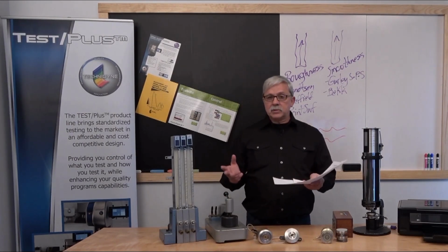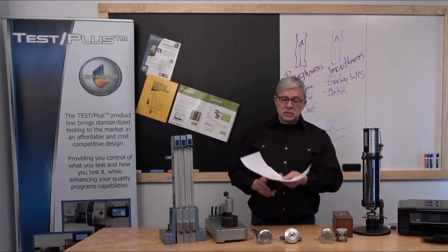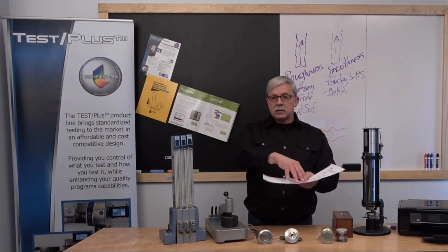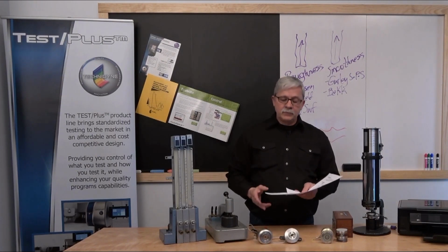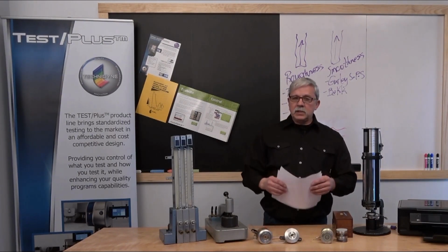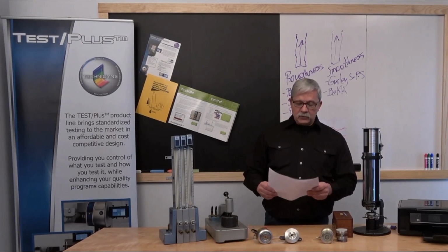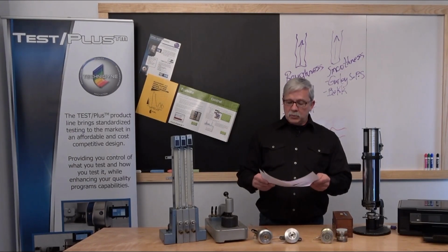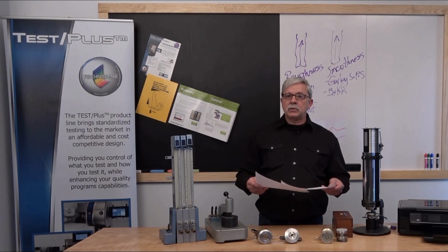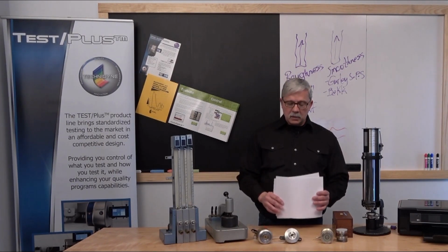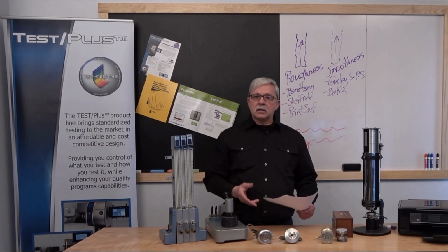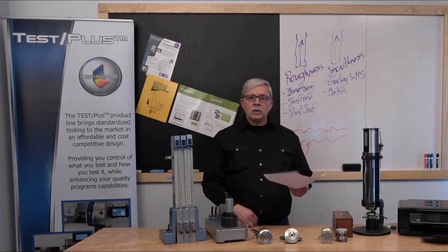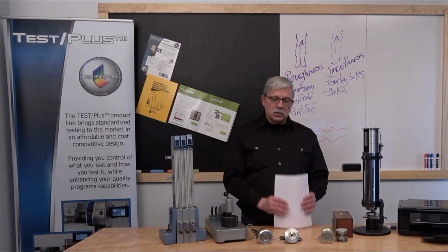I'm sure maybe once in a while you've seen that, where your printer has ejected that document, but it comes out with 2 pages. Some of the document is printed here, some of it's printed here, and so forth. So we all have seen that. The reason behind that is the friction between these two sheets is too high to pull one single sheet through the printer at a time. So that's another really key reason behind identifying what the surface characteristic is all about.